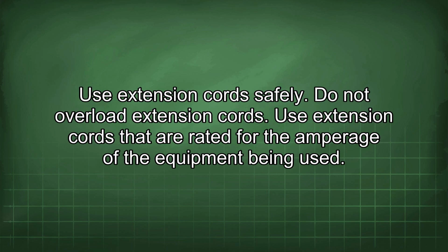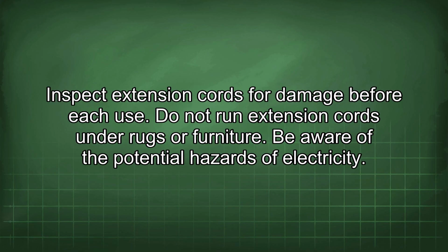Use extension cords safely. Do not overload extension cords. Use extension cords that are rated for the amperage of the equipment being used. Inspect extension cords for damage before each use. Do not run extension cords under rugs or furniture.